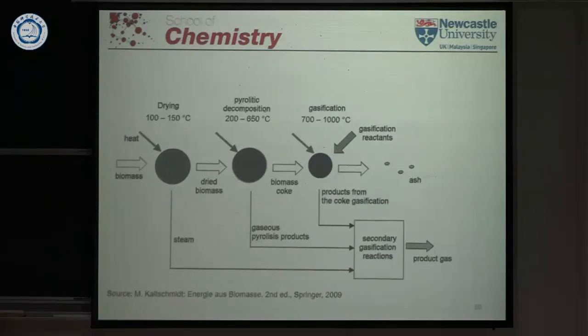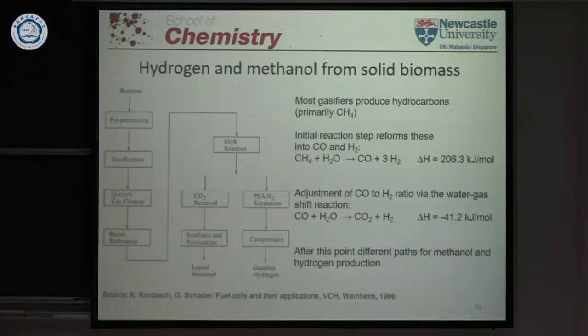So things that you typically throw away, put in a landfill, you can use to make some fuel gas from it. So that would be a process for making hydrogen and methanol from biomass. You see again, this is the pre-product gasification gas, then you need the gas cleanup, so that would be the step after what I've shown you before.